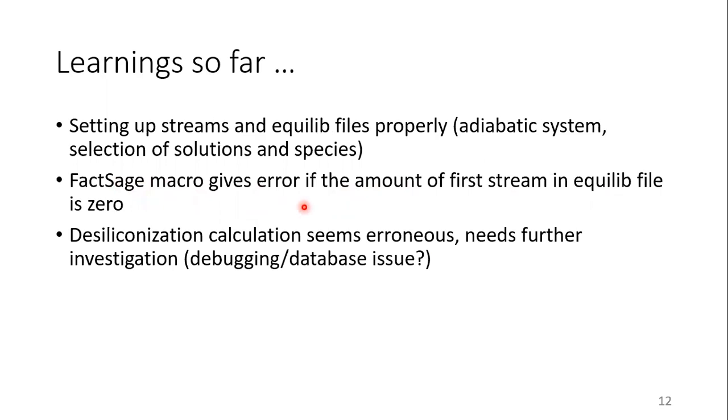More practically, if you have a reaction between metal and gas phase in R2, sometimes you may generate solid silica, sometimes you may generate liquid slag with a few silica combined. So one of those components may become 0, and that gave us errors many times. So one needs to be careful about this.